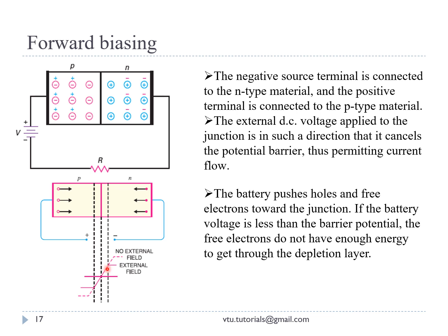As the voltage increases, the flow of electrons and holes also increases. So when the junction is forward biased, there will be almost zero resistance offered for the flow of charge carriers, and this path will give a continuous flow of electrons and holes, which results in the current called the forward current.